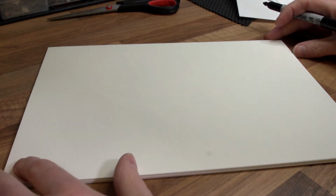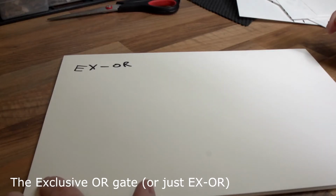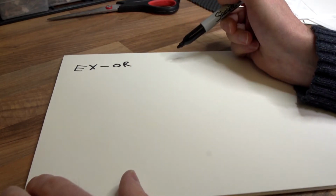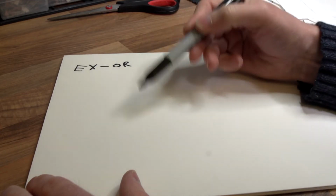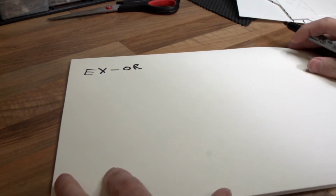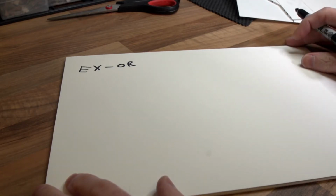There is another gate worth talking about, which we see all the time in electronics, and that's the exclusive OR, or EXOR. And this is a bit of a strange one, but it's used a lot, and it has a lot of uses. It's not the same as an OR gate, whereas any of the inputs would give an output high. An EXOR works on difference of input. So only when there's a difference between the two input terminals, then you get an output of high. You can think of it like a difference indicator. If the two inputs don't match, then you get a true output, you get a high output.